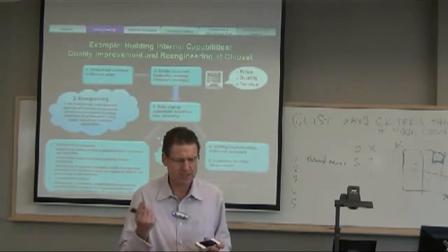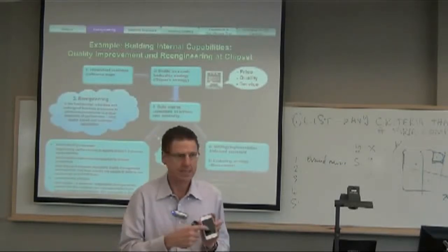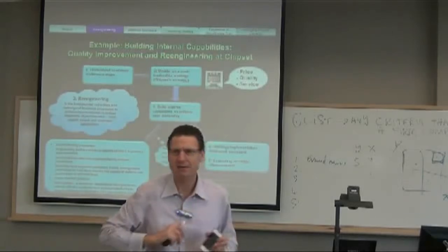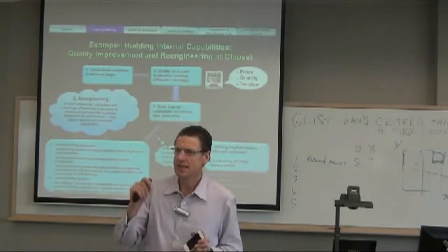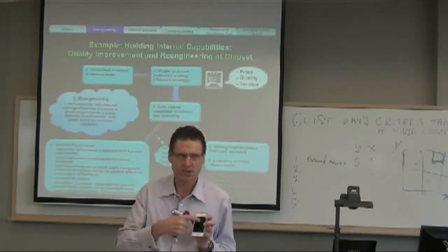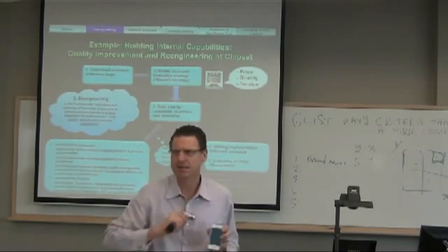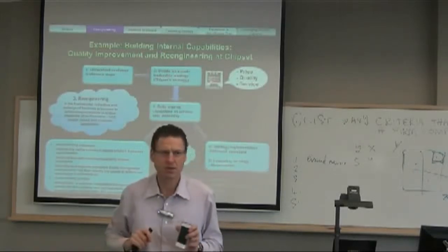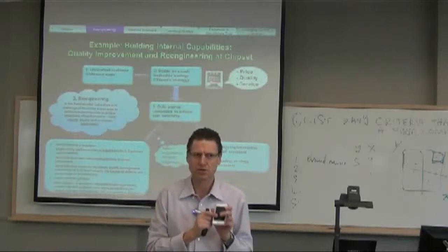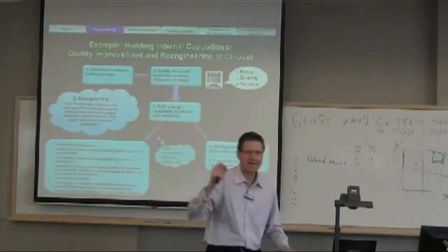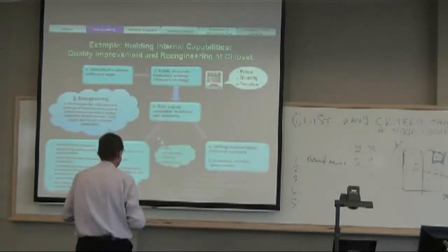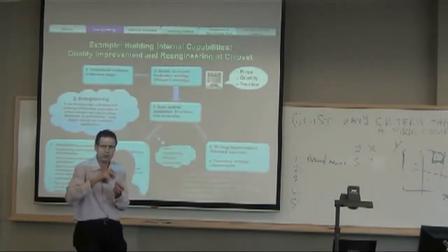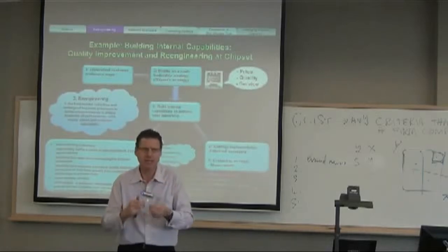You've got the glass, you've got the electrode module that takes your capacitive touch, and then you've got the LCD behind it. The iPhone 5 is able to be thinner because now the electronic module that takes your touch is part of the glass. Okay, so there's only two parts to the LCM module there. There's three parts to this LCM module in this product. And so that is an example of value engineering. So you're actually building value into the product, simplifying it, things like that, okay?